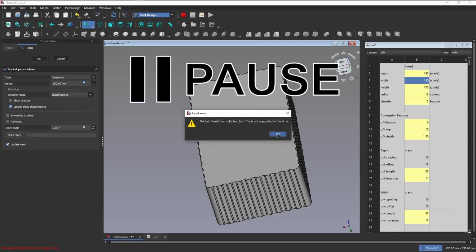I don't know exactly what broke or why. I recreated it a couple times, and it still broke in the exact same way when I attempted to change the size of it. I ended up removing auto remove redundant in the solver, and then I ended up having to recreate it without using the symmetrical feature, instead using a construction circle, which ultimately achieves the same thing. So I'll show you what I did that actually ended up working, and we'll skip all of the mistakes of getting nowhere in a hurry.